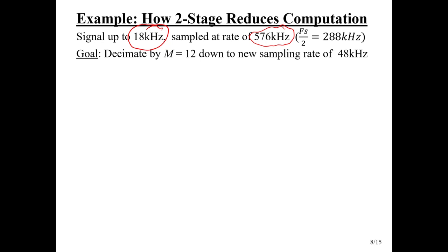And as we'll see, we need to upsample by some level. Maybe not 12, but 12 would certainly work. Maybe it's a very serious distortion that creates some pretty strong high frequency harmonics, and we want to keep all those and not have them alias back down. We'll talk about that later. So whatever the reason, this is where we're at.